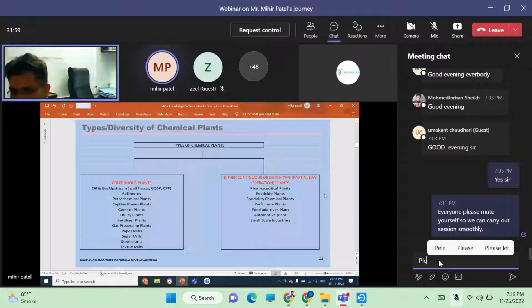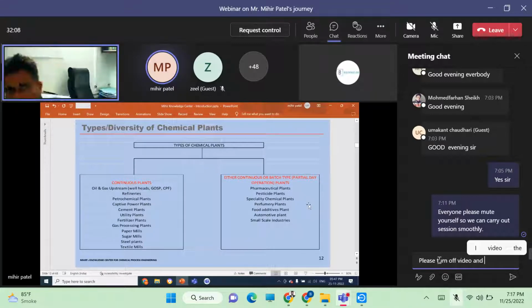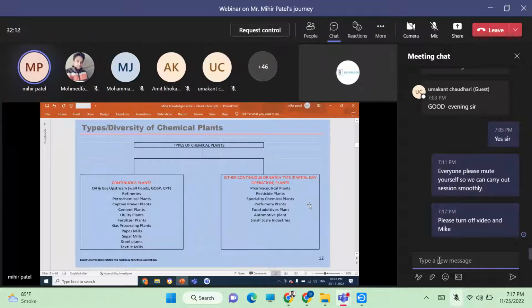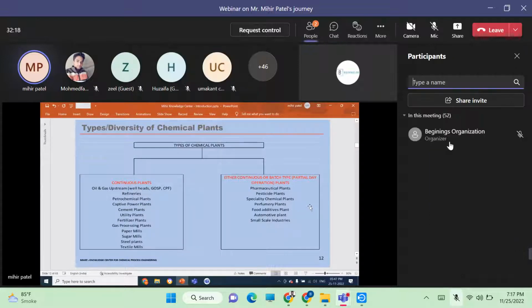different specialty. Like a perfumery plant, for example, you have to be careful while final distillation of the perfume is carried out, because you have to conduct it under vacuum conditions, at very low temperatures. You don't want degradation, for example. Otherwise, if you have charring occurring, then the perfume loses its smell.